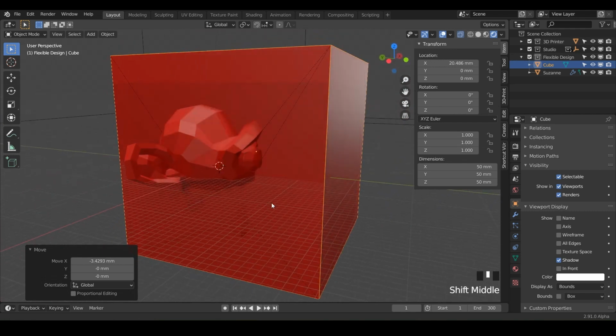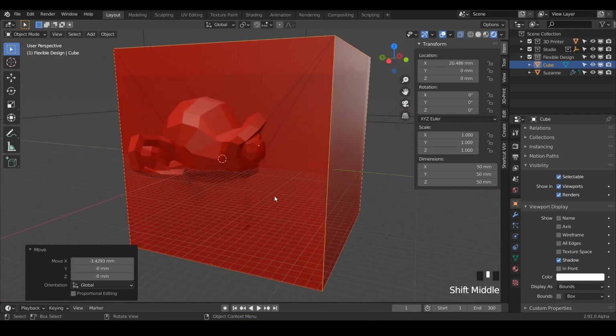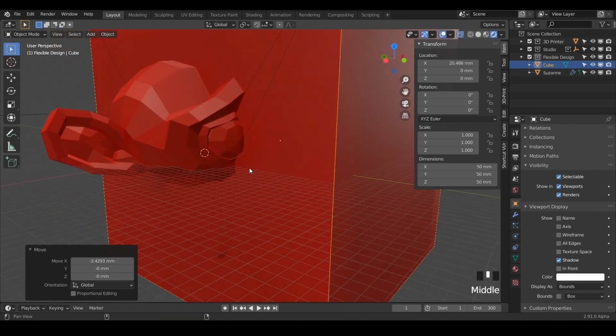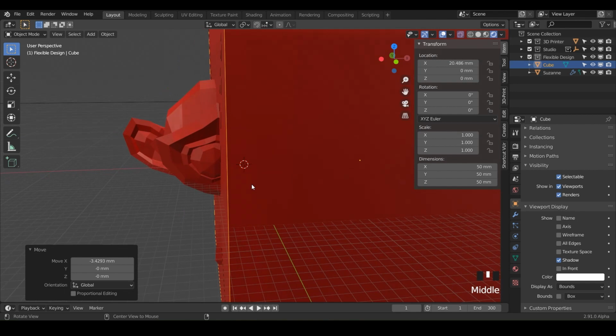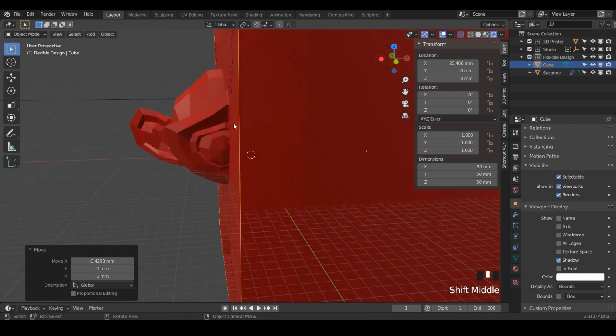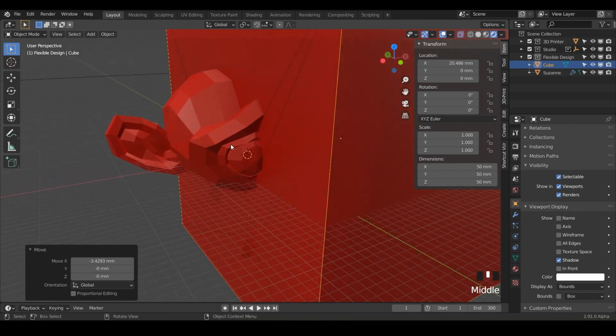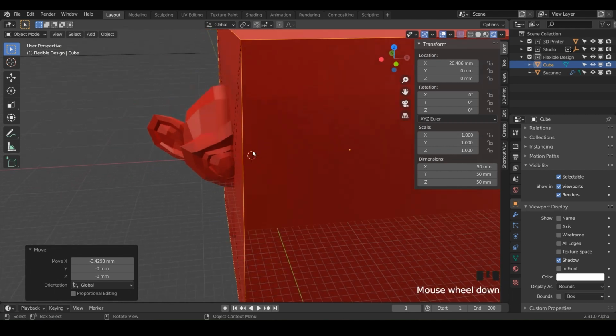The reason for that, and what I want you to understand, is it's not Blender being stupid, it's us being stupid, because we have to, as 3D print designers, understand that it can't make the Boolean operation if there's a big hole in this geometry. So one thing we could do is fix the Suzanne head and make it manifold, and make sure it's all one single mesh, and then we would have no problem Booleaning these.